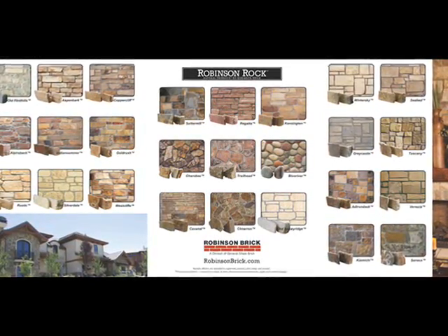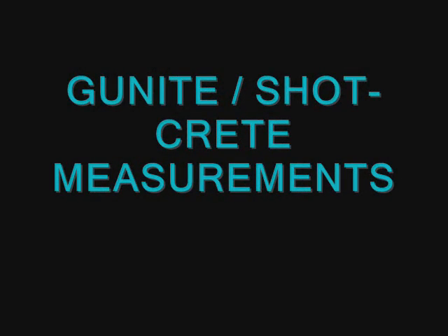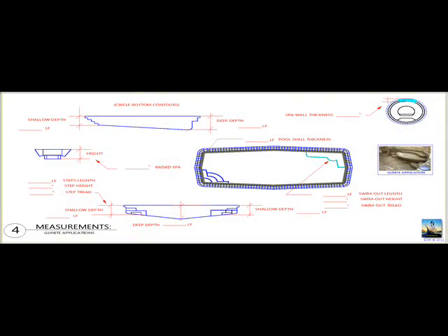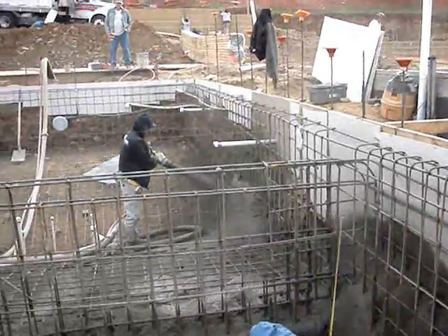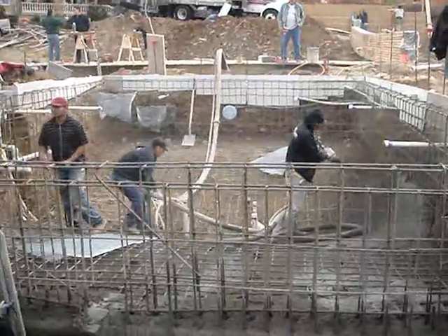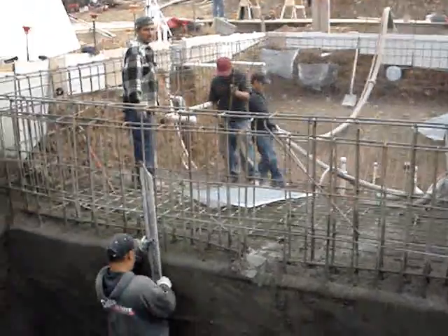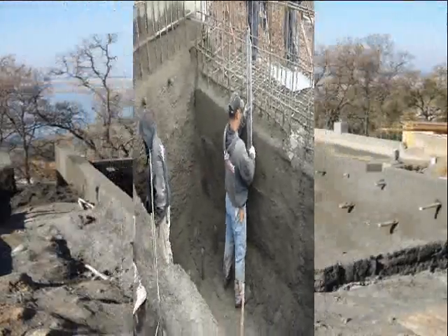Additionally, tiles as well as other products come in different grades. Depending upon the product and grade selection, the pricing of each will be affected accordingly. The gunite or shotcrete product estimated volume will involve projecting the required application that will fulfill the thickness and configuration requirements that have been called for on the approved engineering schedule. This volume will be measured in either a tonnage weight or a volume of cubic yardage unit.